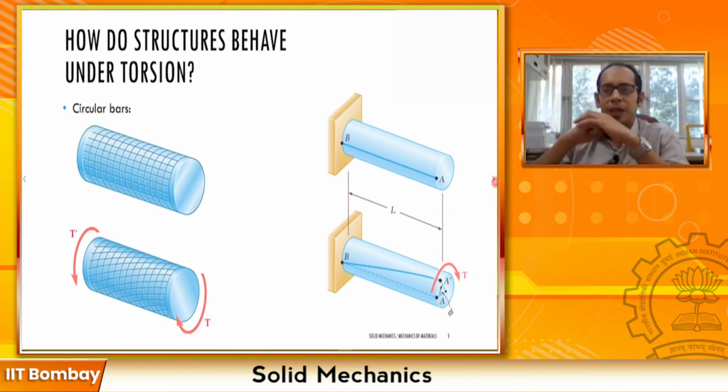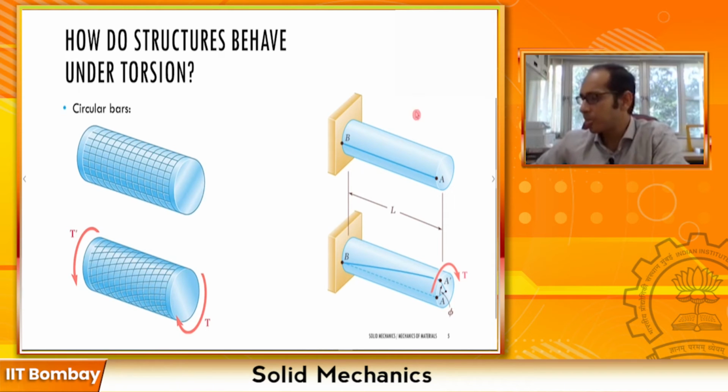So if we have to take a static snapshot of the video that we just saw, and from this figure which we just deciphered, if I have a horizontal line like this, A to B over here, after I'm applying this particular torque T, now here this particular side is clamped, so if you're applying this torque T, what you will develop is an equal and opposite torque at the support as a support reaction at this particular end B over here, right?